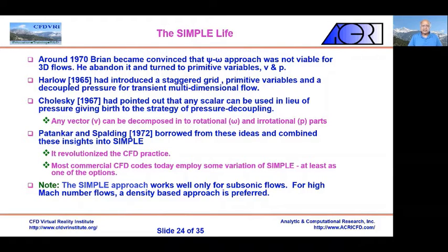So Patankar and Spalding in 1972 borrowed these ideas and combined them into a method called SIMPLE. This revolutionized CFD practice, and most commercial codes today employ some variation of SIMPLE, at least as one of its options. Now, one caution I have here is that the SIMPLE approach works well only for subsonic flow. You can make it work for higher speed flows, but it's like trying to reach backward to catch your nose. For high Mach number flows, a density-based approach is better and is preferred today.